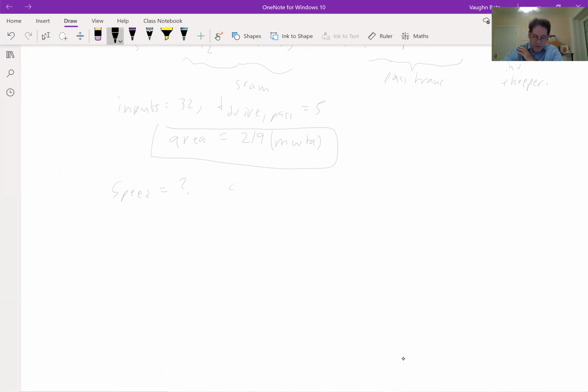Okay, so speed is slower. So we've got a trade-off here. But Kimmy already gave a good idea of, well, why do only the extremes? We've done 1 level, a fully decoded mux or fully decoded SRAM. We just did K level, which is fully encoded, the most levels we could possibly use. We could look at ones in between. So we could do a 2-level mux, for example.